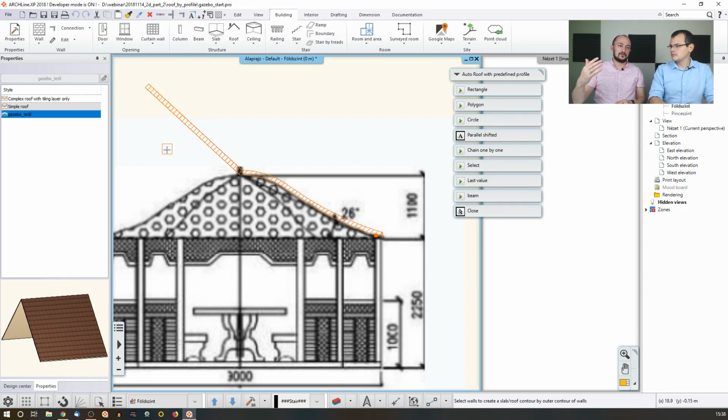Whenever you create an automatic roof, this is the angle at which the roof will be handled. And why is that there? If you defined a half section of anything and you design something wider than this, without this angle the software wouldn't understand how to fill up that gap. Oh, so there could be a gap. There would be a gap. I see. But we don't want to make it an open thing. This is a roof, so it should be fully covered. This is how the software understands that this is how the rest will be filled up.